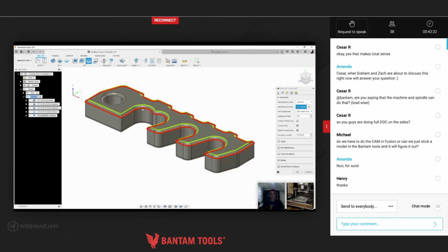If I wanted to edit a boundary, I can click once, single click, and I can select an area like this, press plus, and it'll accept just that boundary here. And click again and delete that if I want to as well. Again, as you can see, it's just click and edit, really quick and easy if Fusion doesn't quite give you the boundary you'd like.